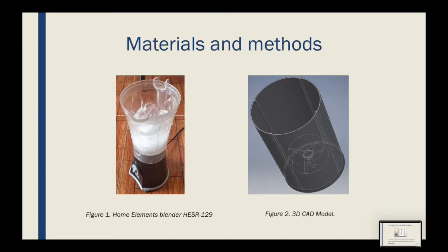In general, to obtain the power curve and for the modeling of the gas-liquid interface, it was necessary to develop a 3D CAD model using Autodesk Inventor that described and represented the blender selected for the study. After this, the geometry was imported into Star CCM+. Then, the rotating solid, corresponding to a solid surrounding the blades of the blender, was separated. Finally, the interfaces were generated and the internal volume was extracted.